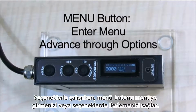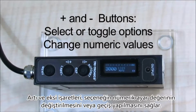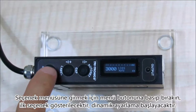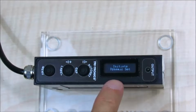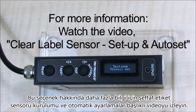When working with the options, the menu button allows you to enter the menu or advance through the options. The plus and minus buttons allow you to select, toggle, or change the numeric value of the setting for that option. To enter the Options menu, tap and release the menu button. The first option will be displayed. Initiate Dynamic Set. Dynamic Auto Set is one of 3 auto set modes discussed in detail in the previous video. For more information on this option, please watch the video entitled Clear Label Sensor, Setup and Auto Set.